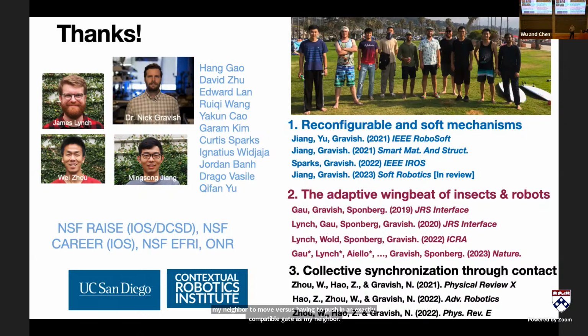We did some studies, at least in simulation, basically taking three links that are driven through a pure feed-forward time-dependent actuation, compressing them into a small space and measuring what joint torques they have to generate to keep their gait going. And it's extremely large. Then you switch them over to this phase oscillator-based actuation, and they immediately synchronize, and the contact forces go to zero.